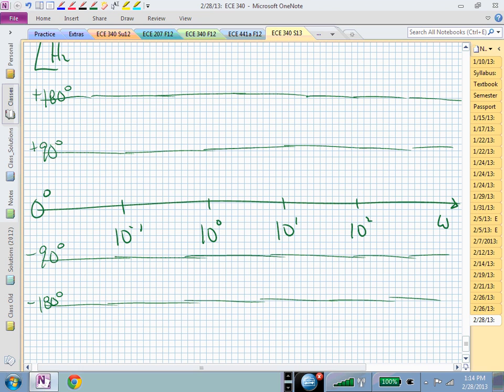Do I need to find some points and then connect the dots? I'm trying to confuse you. It's flat, isn't it? And it's downstairs, and it's at minus 90. This is now the n equal minus 1 angle, or phase plot. That's pretty easy. That's pretty quick. And that's due to one pole at the origin.